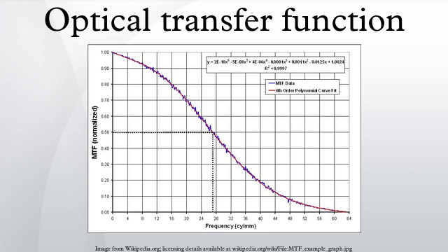The Fourier transform of the LSF cannot be determined analytically by the following equations. Therefore, the Fourier transform is numerically approximated using the discrete Fourier transform, where the value of the MTF is computed over N data points, with an index term for the LSF data pixel position. The MTF is then plotted against spatial frequency and all relevant data concerning this test can be determined from that graph.